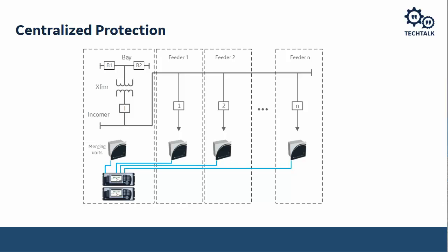You can do something like this with traditional relays and CTs. The drawback is that you're bringing back a lot of copper cable to the cubicles, and that can be difficult to bring back each of the CTs to a central location, strip and close, to do the individual breakers and aux status. So there's a lot of additional copper wire that's being run.